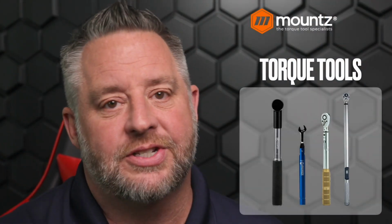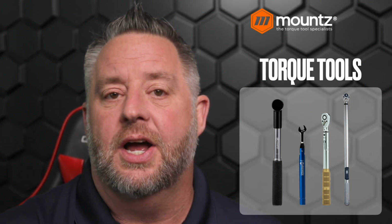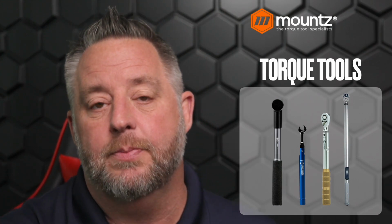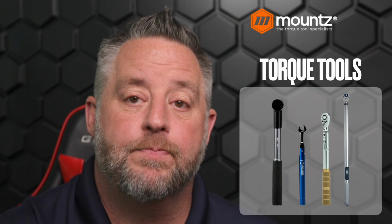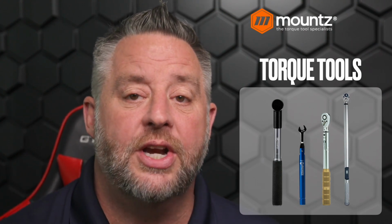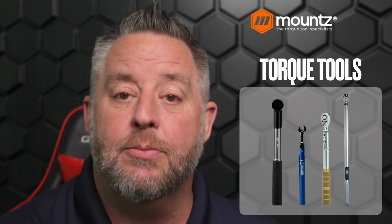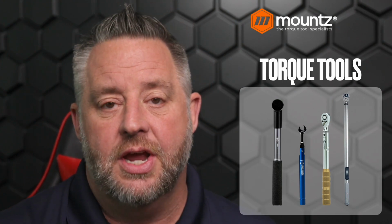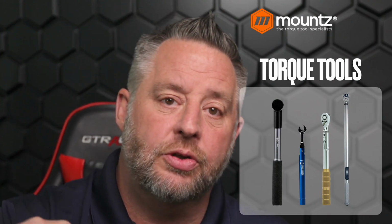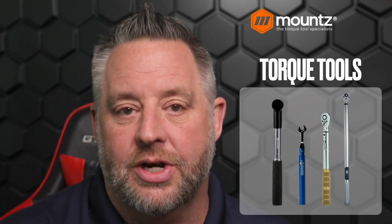Now, there are different styles of screwdrivers. There are adjustables and presets, and those can work with the same clutch mechanism that we have as well. Now, our next type of torque tool is going to be the torque wrench. If we look at this basically from left to right, we have a cam over style of wrench, which acts very much like a screwdriver does. When that wrench is pulled, it goes to a certain value and then the torque is achieved and that wrench simply slips.